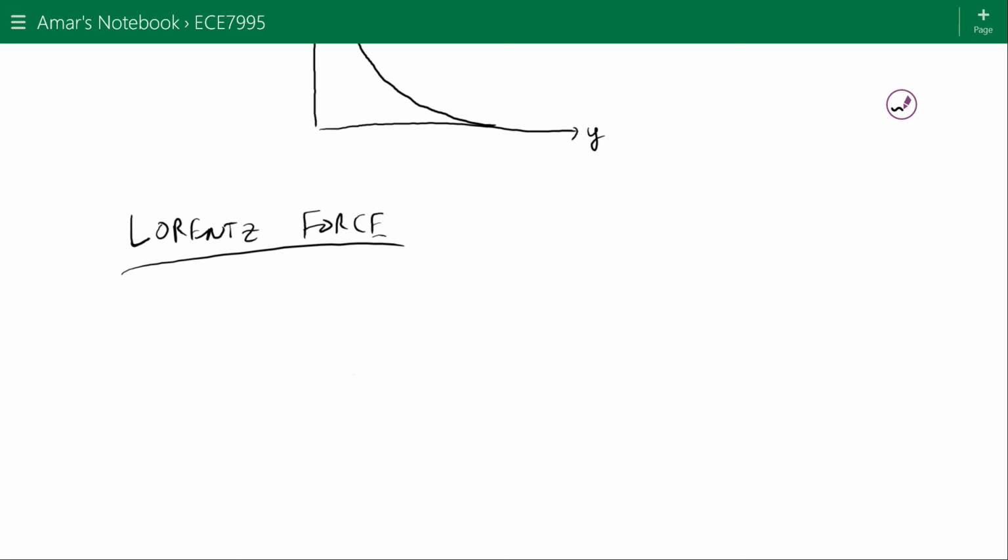Right. And what is a Hall sensor used for? It's used to detect magnetic fields. But it's also used for semiconductor characterization, which is probably the context where you may have learned it. And you can use it to characterize the number of carriers in a semiconductor.